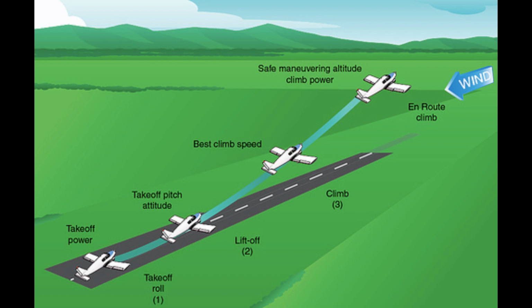If flying a turbojet aircraft equipped with afterburner engines, such as a military aircraft, pilots should advise ATC prior to takeoff if intending to use afterburning during the climb to the en route altitude. Often, the controller may be able to plan traffic to accommodate a high-performance climb and allow the pilot to climb to the planned altitude without expedite clearance from restriction. If you receive an ATC instruction and your altitude to maintain is subsequently changed or restated without an expedite instruction, the expedite instruction is cancelled.